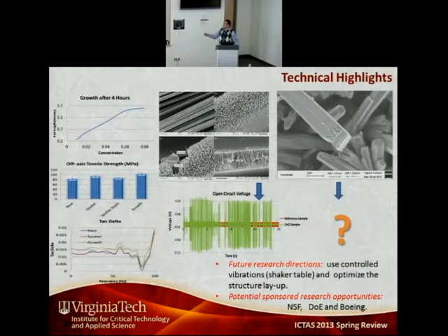So in addition to that, we see here that the nanowires facing each other will induce more friction in the structure. If we have more friction, of course, we get more damping. And if we analyze here the damping properties of our sample using the dynamic mechanical analysis, the DMA, we see that the tan delta, which is a measure of the damping within a viscoelastic material, we get 20% improvement between the growth sample, the green one, and the neat sample.